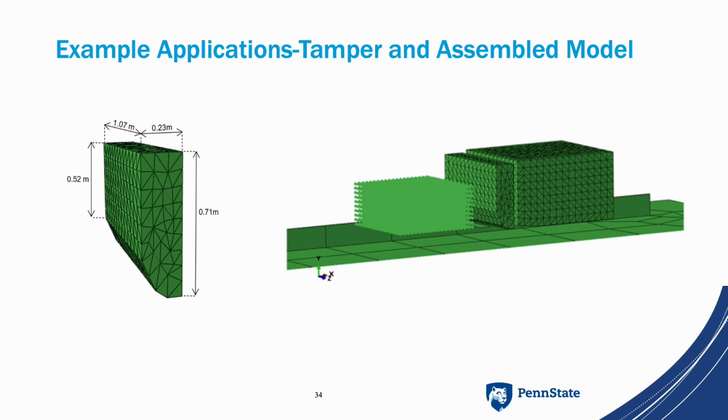So in this study, the other parts, including the base and the paver, were created and discretized by FEM. The base that was ready to be compacted by the paver was simplified to a shell 3.42 meters wide and 17.14 meters long without thickness, on which two shells 1.4 meters high and around 1.14 meters apart were created as a fence to designate the paver's work path.